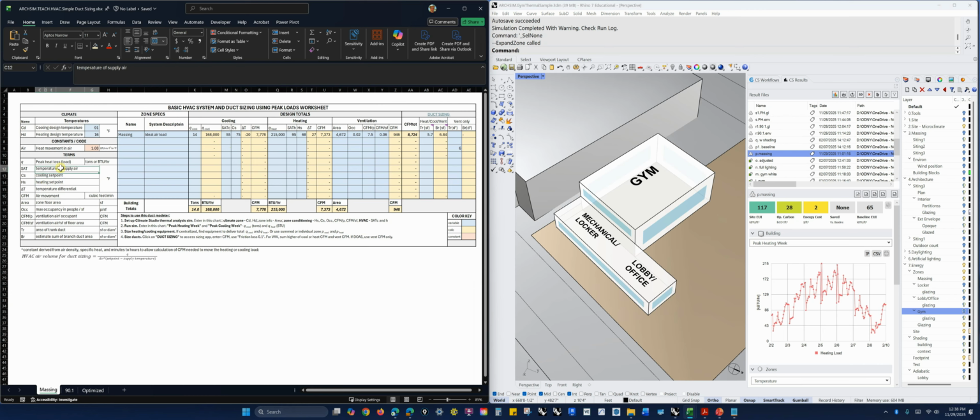So hopefully this will be a helpful chart. Okay, so I have a supply air temperature for cooling at 55 degrees. I would use that because that's a good rule of thumb. And my set point is 75 degrees. So the delta T between the air that I'm delivering and my set point is 20 degrees.